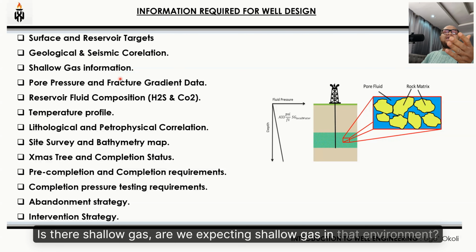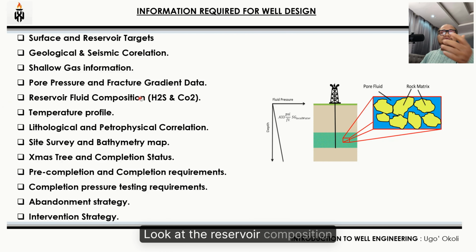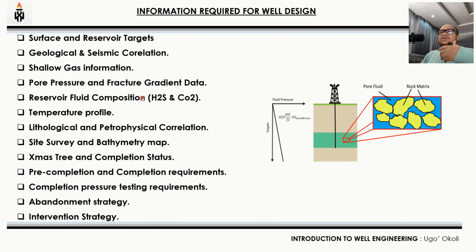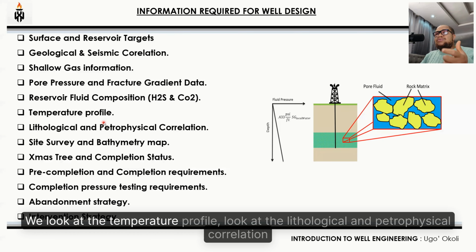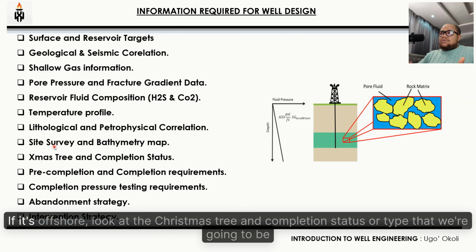Are we expecting shallow gas in that environment? Look at the pore pressure and fracture gradient data. Look at the reservoir composition. Is it sweet? Is it sour crude? We look at the temperature profile. Look at the lithological and petrophysical correlation. Site survey and bathymetry map if it's offshore.